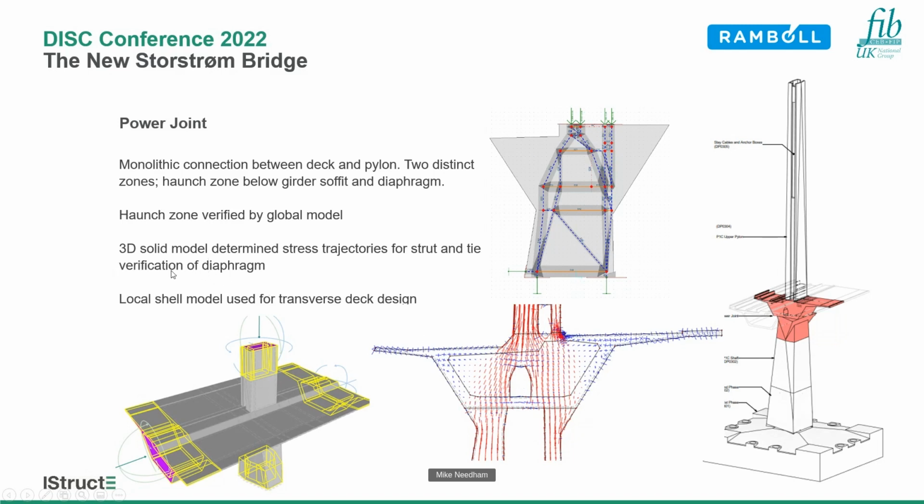So for this, we used a 3D solid model to determine stress trajectories for strut and tie verification. We also used a local shell model for the transverse deck design.